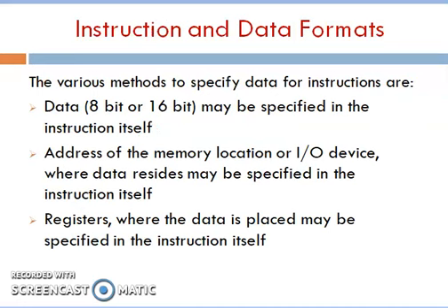Next we can see the instruction and data formats. There are various methods to specify the data for an instruction. The data may be specified in the instruction itself. That is, the data is a part of the instruction. Immediately after the opcode, the data is coming.